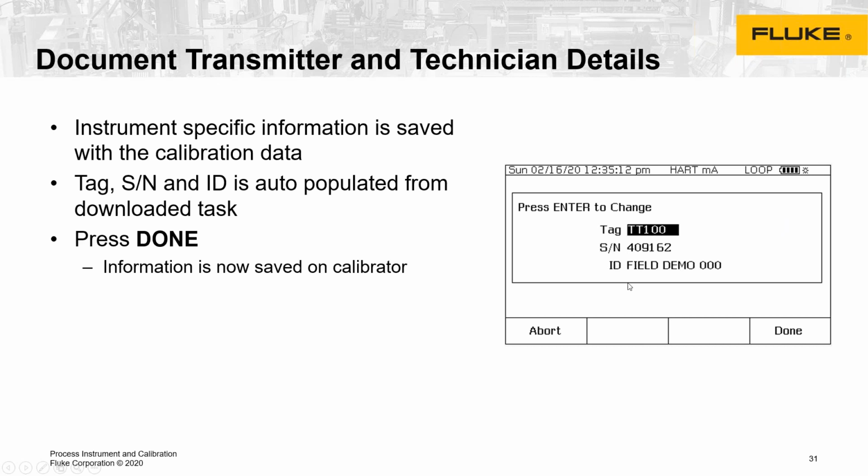The next part, it will show what the tag, serial number, and instrument ID used are. This is where the technician could enter their employee number or their name to denote that they did the calibration.